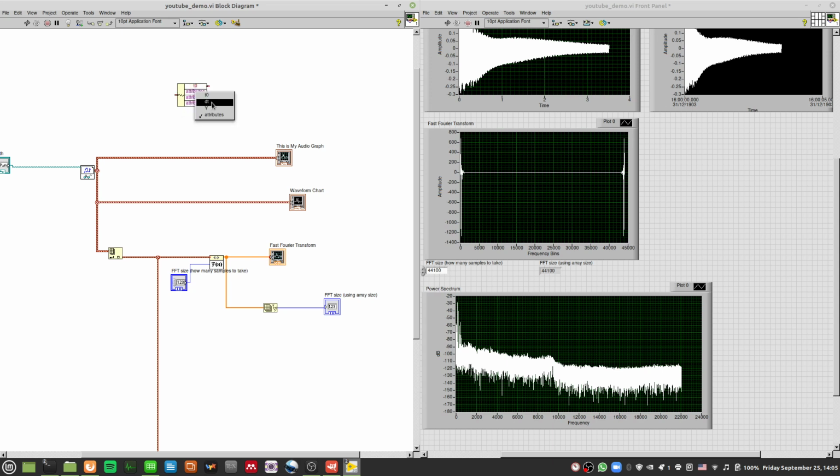The second one I want to put as DT. Same as anything that has the attributes function, you can just select. So click the T0, I can select T0, DT, or Y. And the last one I will just want to select Y, and then I'll leave it as such. This is how you get data out of your waveforms.